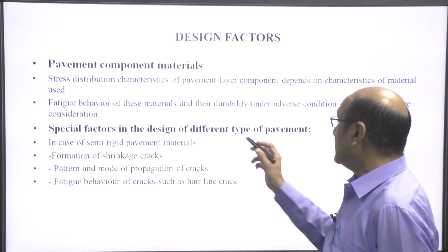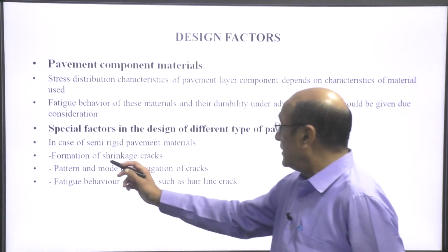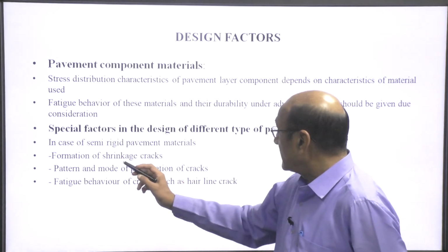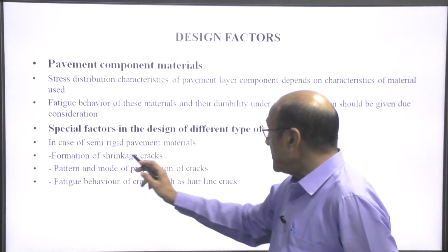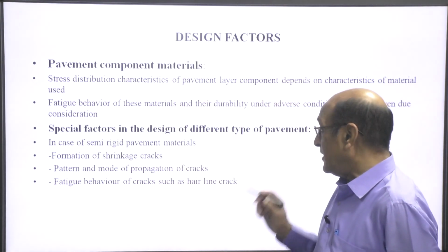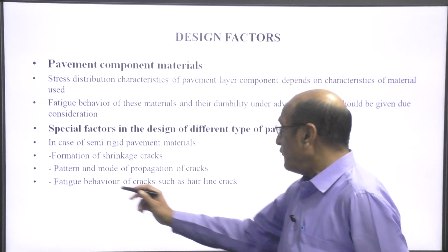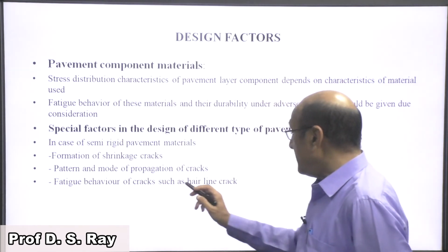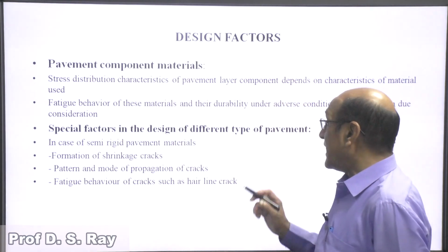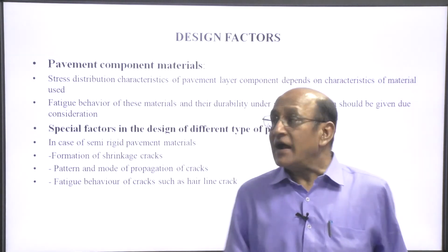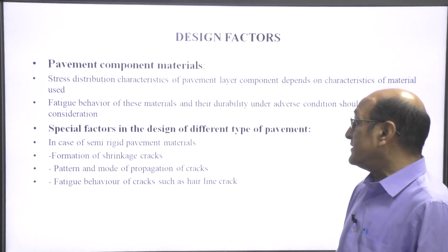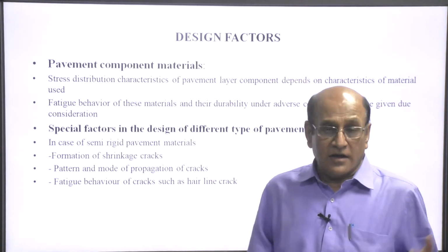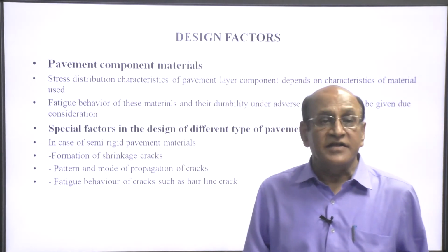Special factors in the design of different types of pavement: in case of semi-rigid pavement materials, the formation of shrinkage cracks should be taken care of, the pattern and mode of propagation of the cracks, and fatigue behavior of cracks such as hairline cracks, etc. So, these are the special factors that should be considered while designing either the flexible pavement or the rigid pavement.